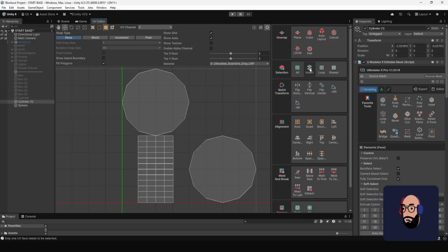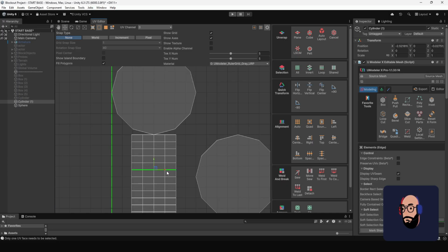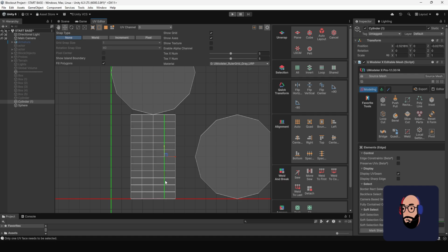Now, if I hit invert, in this case, it's going to unselect because it's inverting the selection. But if I were to select just these few and then hit invert, as you can see, it's just inverting the selection. Now, for instance, if I were to go to the edge tool and I want to do a loop, you notice it selected the loop as opposed to just that one. And so for instance, if I select the edge here, it should select the loop there. It just depends. There we go. And so now we selected that loop.